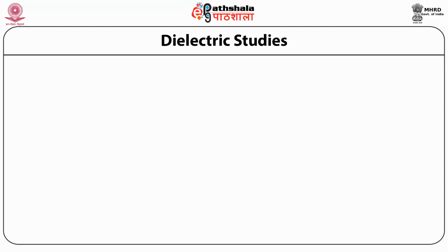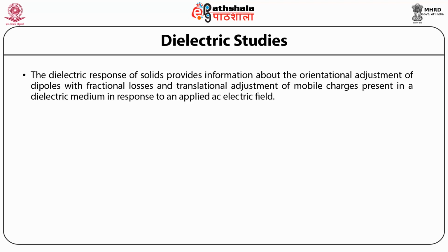We next take up the dielectric studies. The dielectric response of solids provides information about the orientational adjustment of dipoles with frictional losses and translational adjustment of mobile charges present in the dielectric medium in response to an applied AC electric field.